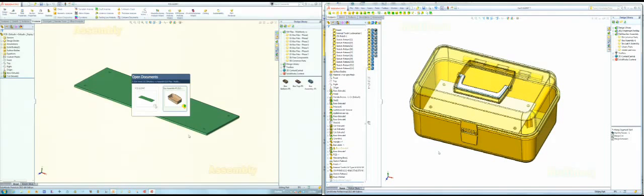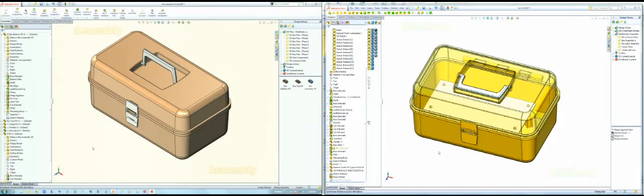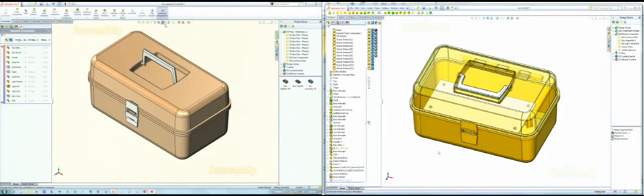Now the other trick here is we know that to assign materials, I could go in and add materials part by part. But we have assembly visualization when we're in an assembly. We can make a column that's SolidWorks materials, and there's a thing in here to say add a column, and you can define what the column is. In 2013, we can have additional columns.